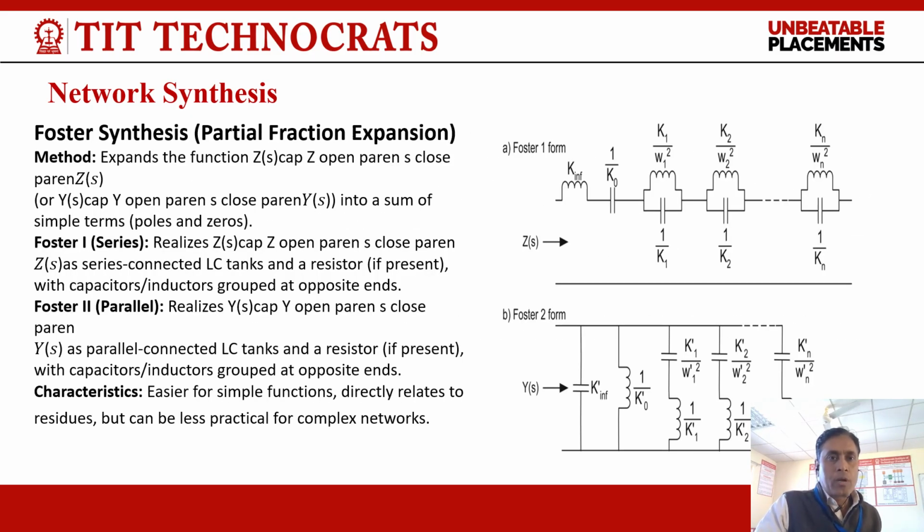If we talk about Foster synthesis, that is realized by partial fraction expansion, it expands the function Z(s) or Y(s) by s into a sum of simple terms.